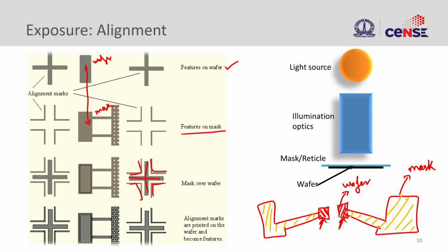It is impossible to do this structure by structure. You might have hundreds of devices on the mask. It is impossible to align each structure. So, it is better to put alignment markers and then only align the alignment markers, which should take care of device alignment as well, because this is all relative positioned. So, once you have this one, and then you can align this, and then you put the contact and start illuminating, and you should be able to get the aligned illumination that you are looking for.